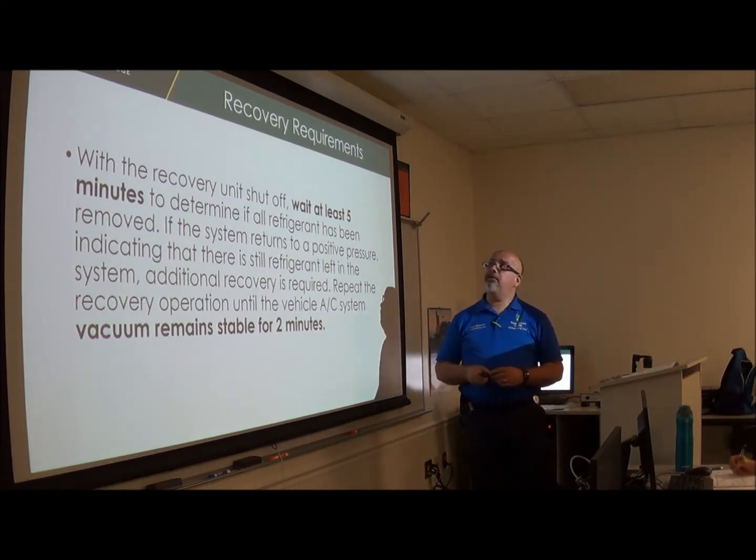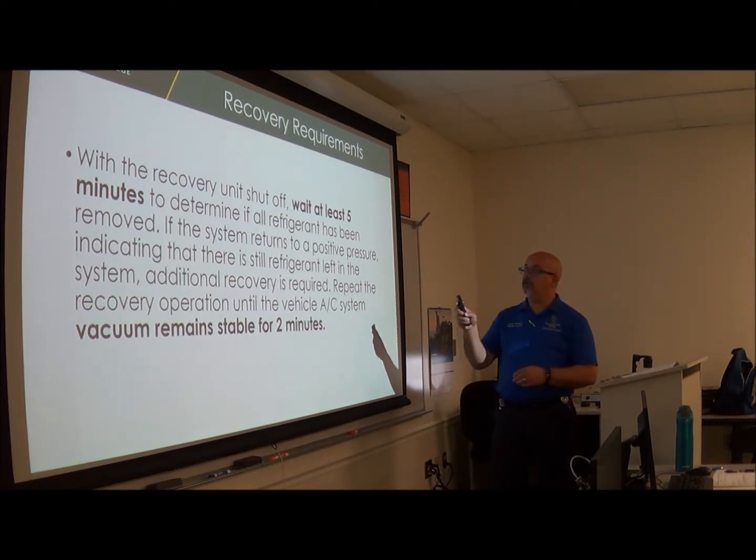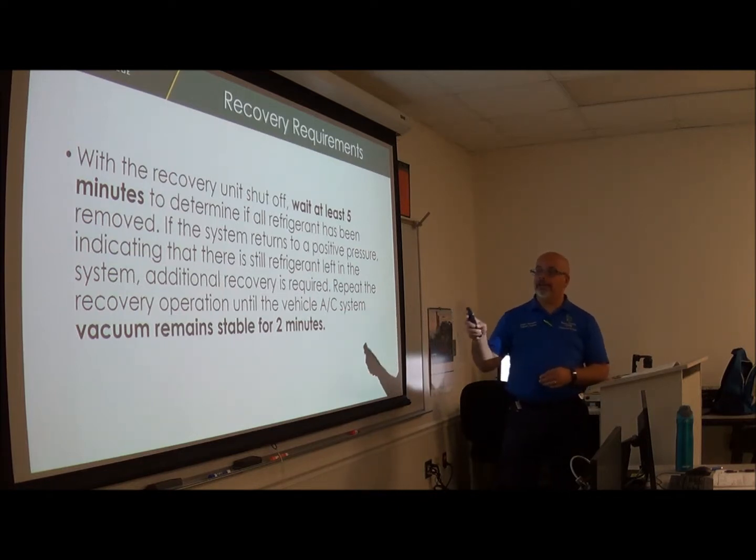With the recovery requirements, with the recovery unit shut off, wait at least 5 minutes, that's what I mentioned before, to determine if all refrigerant has been removed. If the system returns to a positive pressure, indicating that there is still refrigerant left in the system, additional recovery is required.